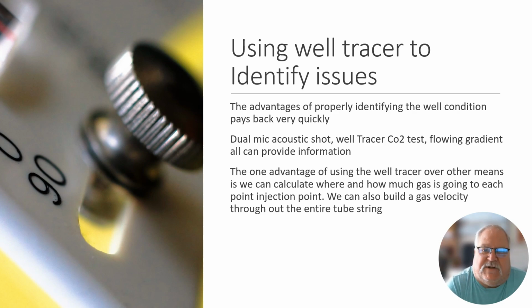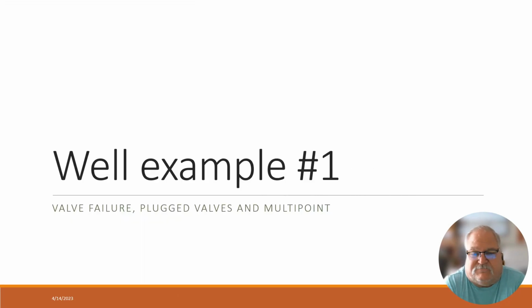Or you may create a case where it justifies doing a rig workover, removing a bunch of those valves or redoing them. Probably if you're at the point of gas-assisted plunger lift, you may only need 1 or 2 valves, or maybe you just need an orifice just below where the plunger is sitting, and because you can reduce so much gas injection, you might be able to cut your injection by 70-80%, or on a lot of these wells practically no injection is required, if any, and we can make it go.